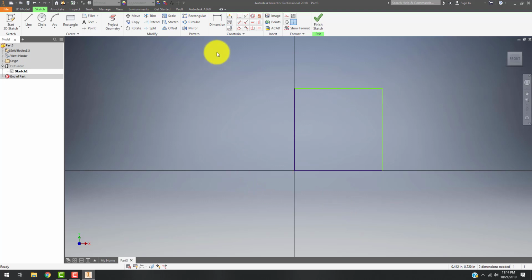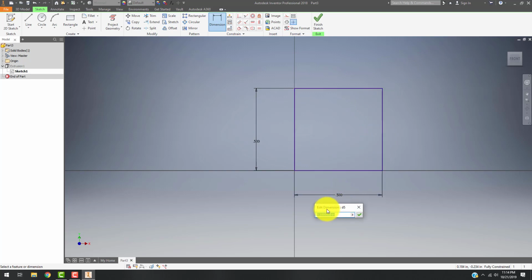There are other ways to add dimensions. You can go through and add it from the endpoint to the endpoint. So I can add that as 0.5, or I can add it from one side to the other. It does the same thing. So there's multiple ways to go through and draw those. If I wanted to as well, when I'm creating my lines, I can add all of my dimensions right away. If I know what the dimensions are, it's really easy to do so.